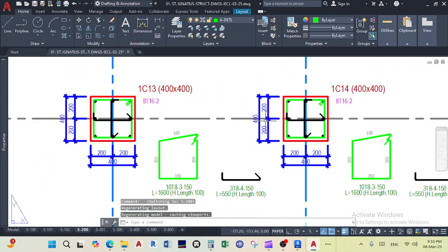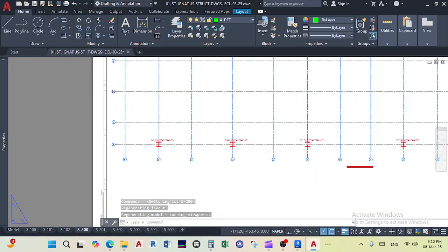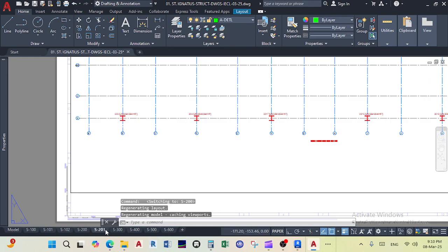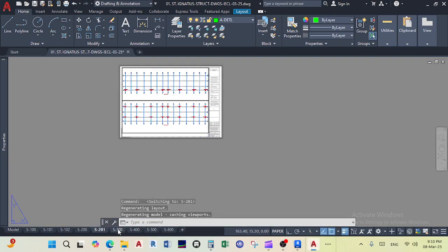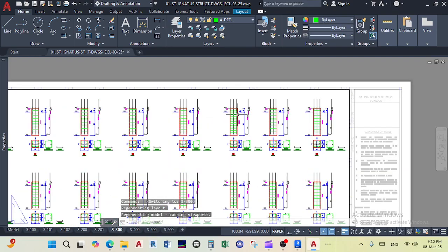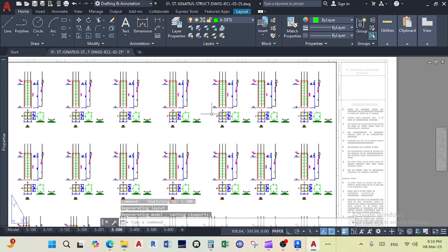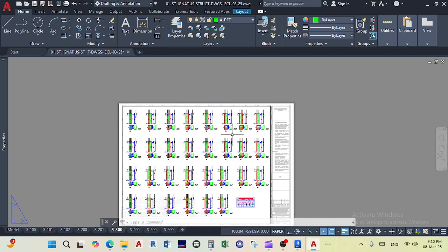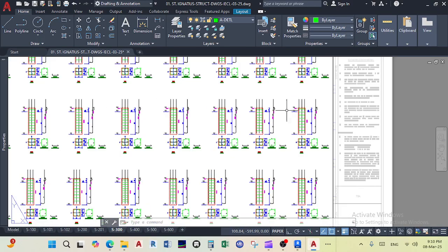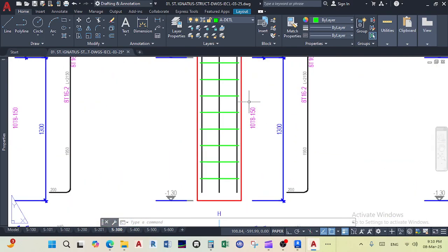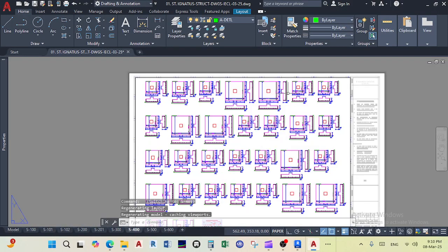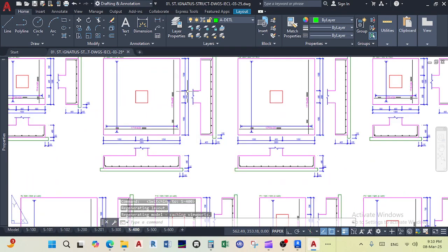And then we've got the section, that information, the canopy columns again, and then 300 shows the column elevations for the concrete, but we do not have column elevations for the beams. So how you get the column elevations for the beams, you need to go into Prota Structure. Maybe that's something that we can discuss later at a different time.